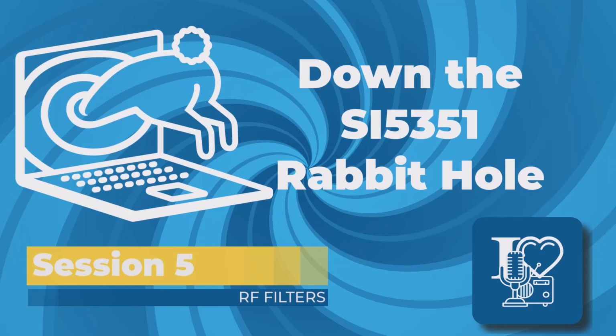One of the things you need to always be aware of is part of the FCC regulations that apply to us as amateur operators: we are required by regulation to always have a clean signal. That means we need to use RF filters to make sure our signal doesn't broadcast across multiple bands via harmonics. So we're going to actually go through that.